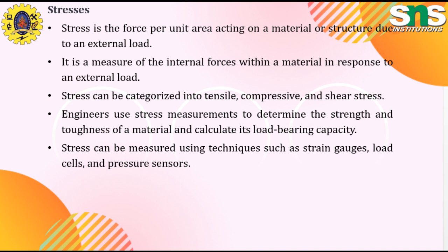Stress is an important factor in the analysis and design of structures and materials. By measuring the stress of the material, engineers can determine its strength and toughness and calculate the load that it can withstand without deforming or failing. Stress can be measured using various techniques such as strain gauges, load cells, and pressure sensors.